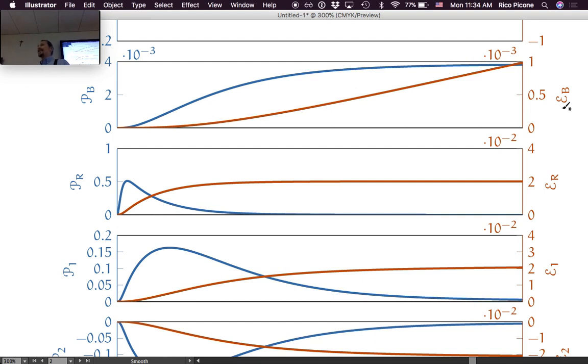So most of the time in steady state, we don't worry about heating that much, as long as that steady state is not one that requires the current to be significant. So if you hold on to the flywheel, don't let it turn, and you put in some non-zero voltage, it's going to want to turn, and a lot of current will flow, a lot of torque, and it will heat up significantly. But when the flywheel is free to rotate, it should be fine.